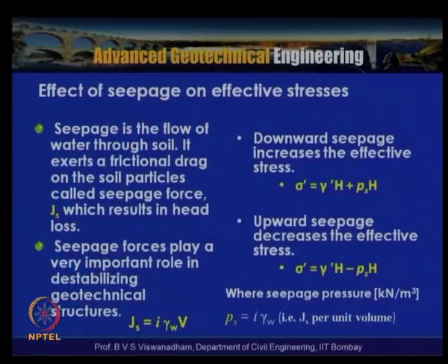So, what we have understood is that seepage is the flow of water through the soil, and it is a phenomenon which happens in soil, and it exerts a frictional drag on soil particles, which is called the seepage force, which results in a head loss. And the seepage force plays a very important role in destabilizing geotechnical structures, and the seepage force per unit volume is called the seepage pressure.